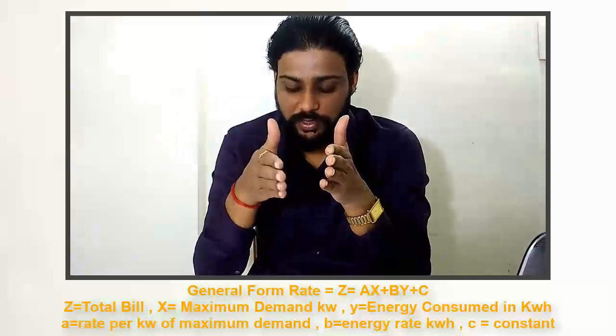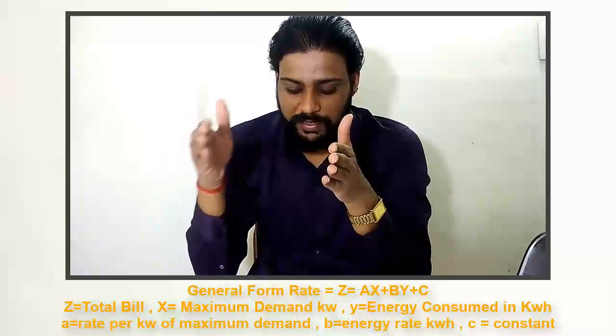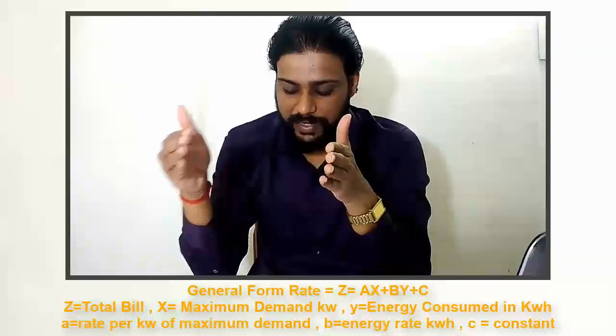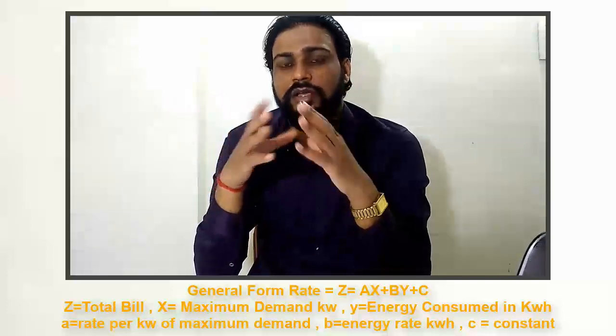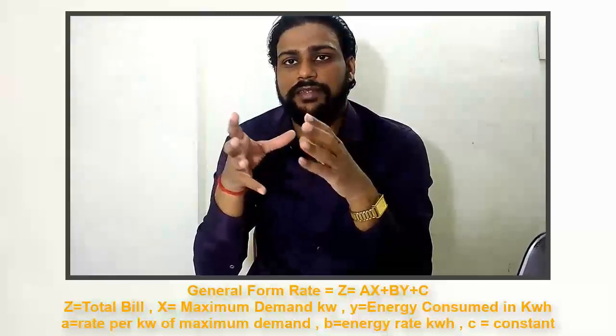So Z is your total bill for the period, X is the maximum demand in kilowatts, and Y is the energy consumed in kilowatt hours. A is the rate per kilowatt of maximum demand, B is the energy rate per kilowatt hour, and C is a constant amount. So this is just one of the ways in which a tariff can be structured.